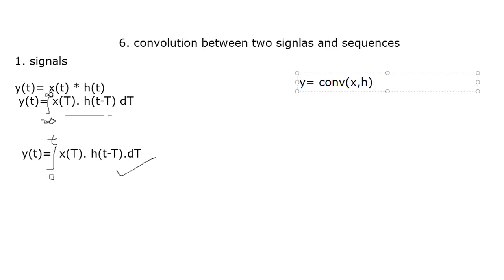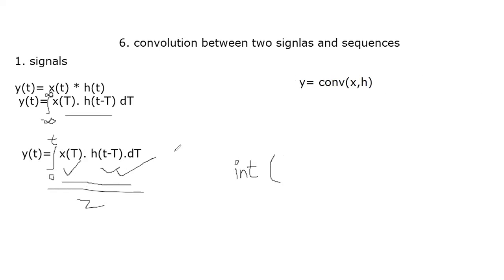I am going to give the first input signal, I am going to give the second input signal. After that I am going to multiply these two. After multiplying the two functions, I am going to use the keyword which is available, integration, just for implementation of the integration in this expression. Integration of what? Suppose this product I represent using some other variable, z. With respect to what are we doing integration? t over the range limits 0 to t. So 0 comma t, like this I am going to write.